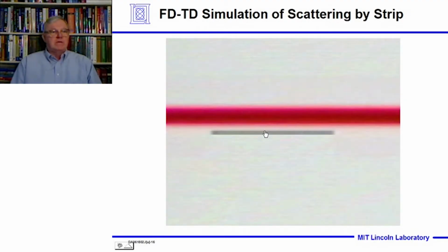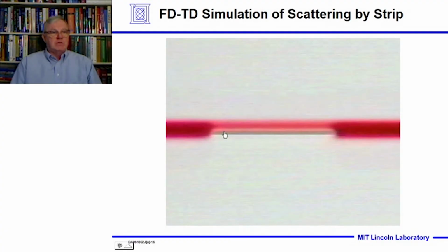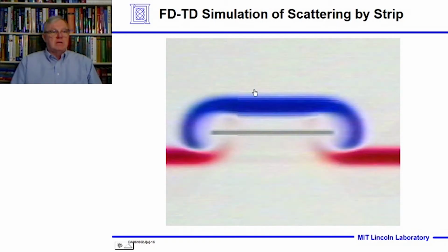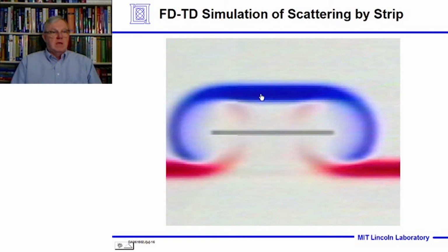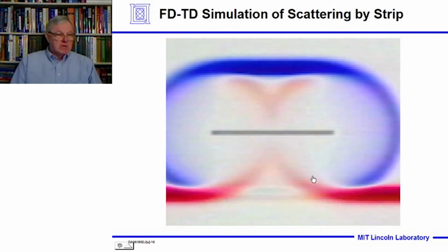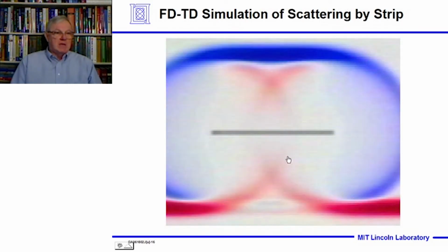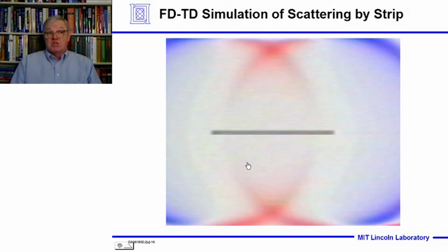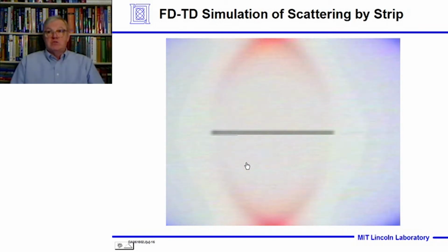Can't have an electric field in here, so we have to generate some induced currents. They're induced. Bingo! They generate an electromagnetic field. And that's the reflected specular wave. But notice that some of the energy is behind it. In the propagation lecture we talked about diffraction, how some of the energy can go behind an object.